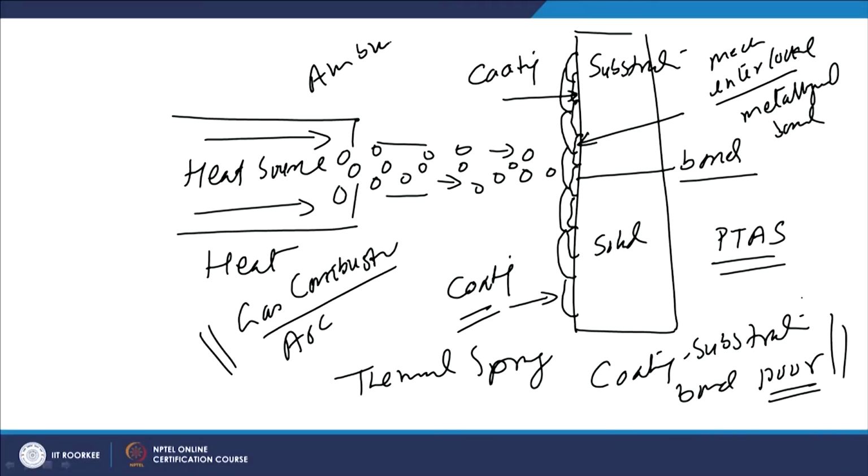If the melting of the material being applied as a coating over the substrate using a thermal spray process is achieved under normal ambient conditions, then there will definitely be a possibility of interaction of the molten metal of these particles with the atmospheric gases, and so a possibility of formation of inclusions as well as the presence of pores between the different particles and different layers being deposited over the surface of the substrate.